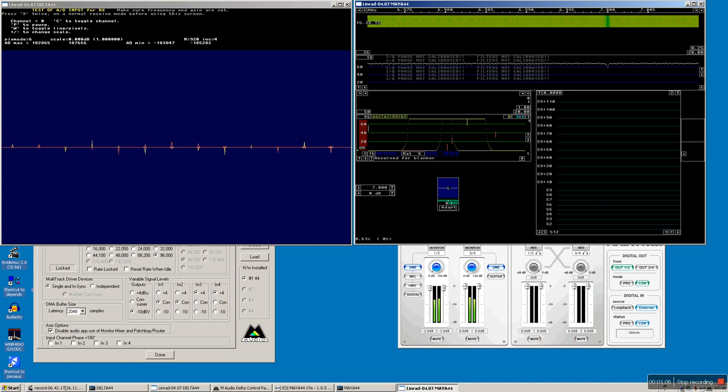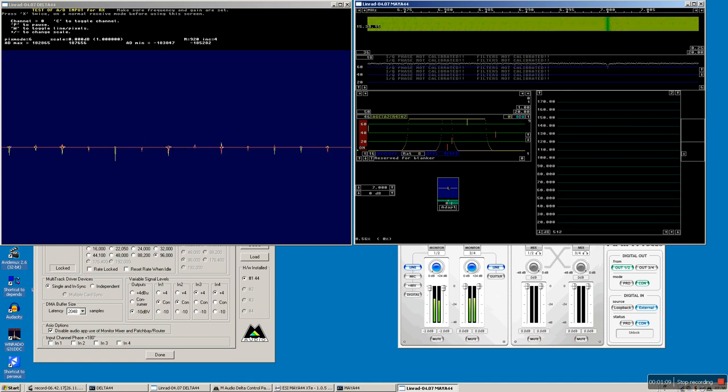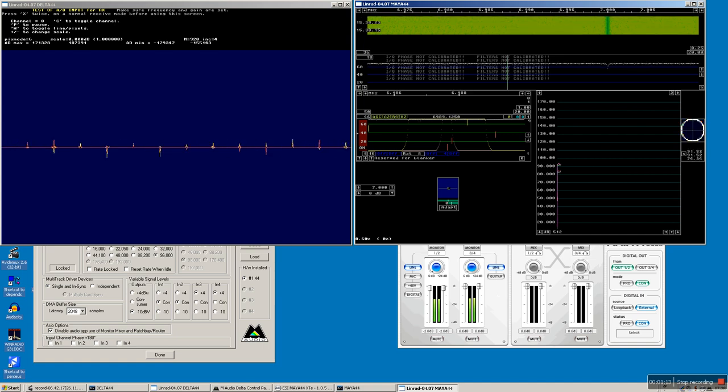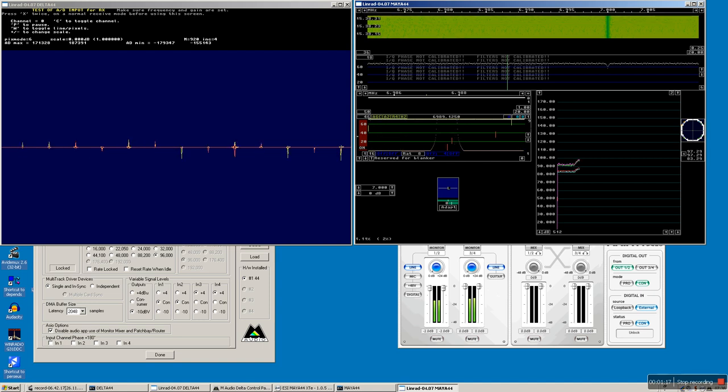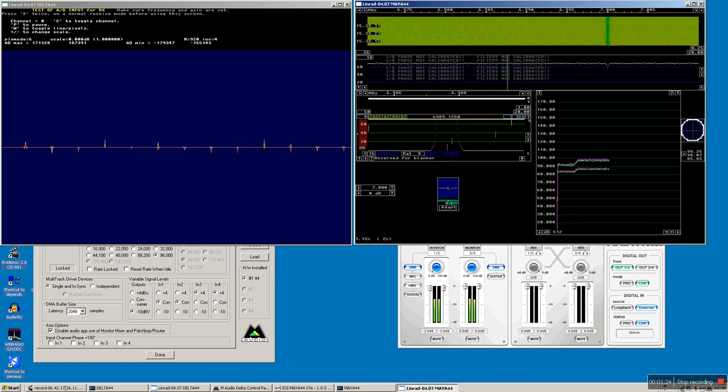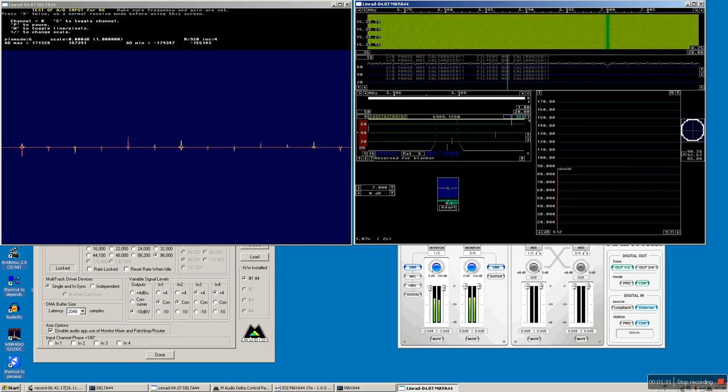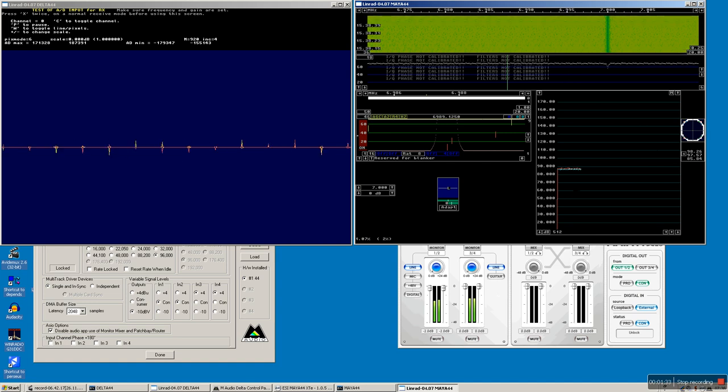It can be set to decibels, and I click on a frequency somewhere, open the bandwidth a bit for better statistics, and then I want to look at the RMS noise, that is like this. And I have an attenuator, so I attenuate by 10 decibels now.